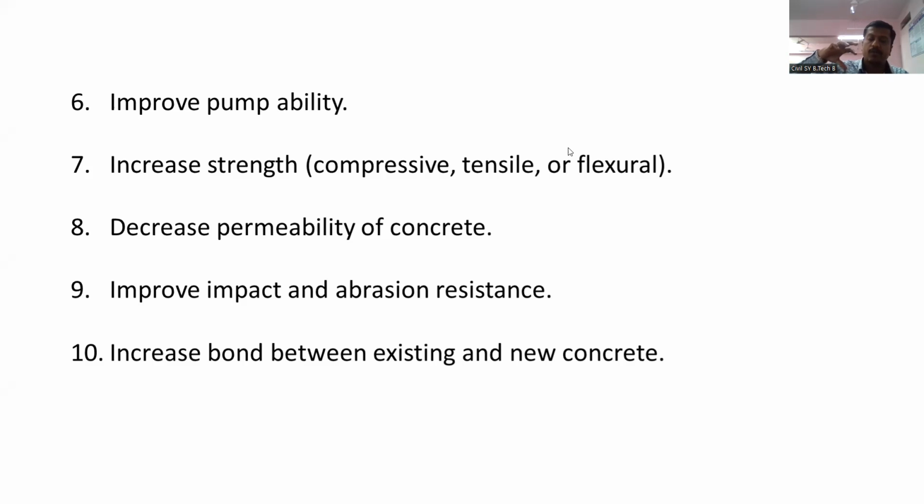Now, if the workability of that concrete is very low, that means you are using less water. Will it be possible for the concrete pump to pump that concrete to a higher height? Definitely not. If you are using concrete of low workability, we can't pump that concrete from one height to another, from 0 meters to maybe 10 or 20 meters.